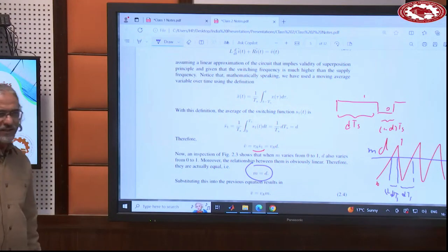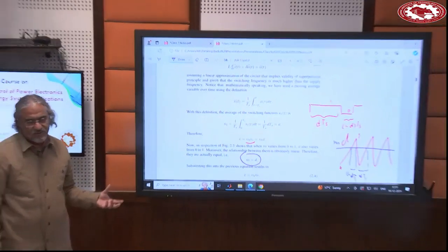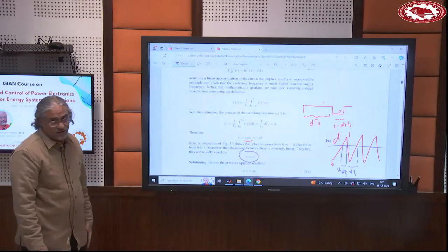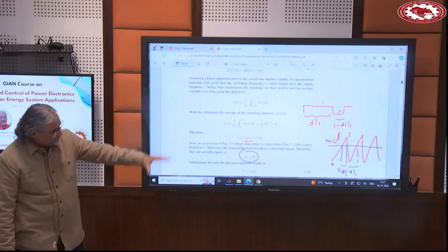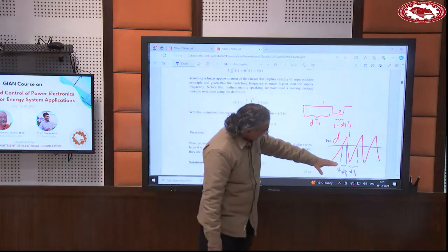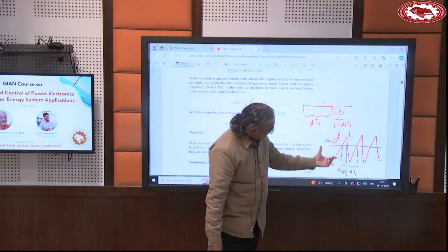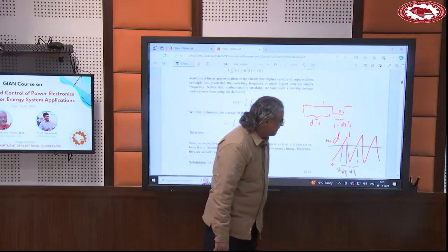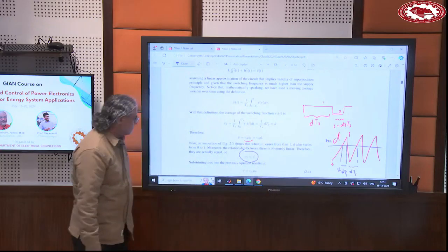So the modulation index and the duty cycle in PWM is the same for buck converter, at least with this terminology that we used here, as long as you are using these ranges from 0 to 1, and then M, you define M just like that. Okay.